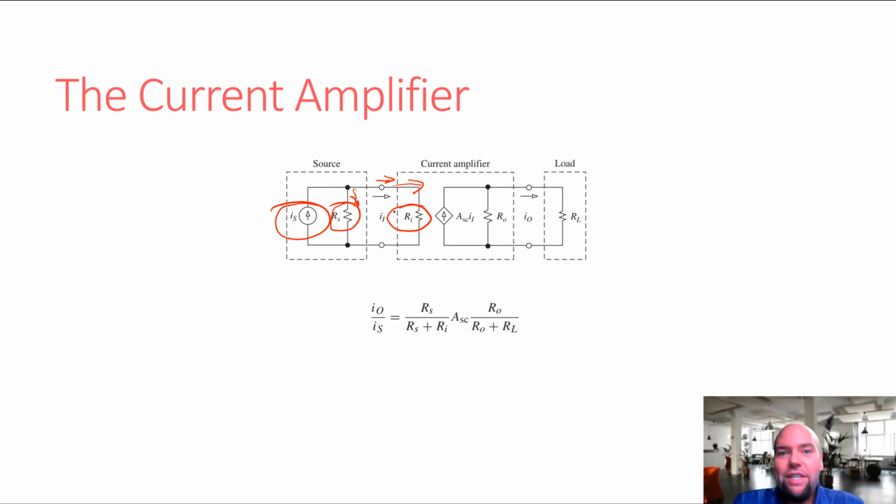But if you have a very high resistance, say you have 20 milliamps flowing into 10 kiloohms. Well, if you have 20 milliamps flowing into 10 kiloohms, it's going to take 200 volts in order to achieve that. Let me see if I'm doing that right. 20 milliamps, 10 kiloohms. Yeah, it's going to take 200 volts. So basically, that current supply is going to have to build up 200 volts to maintain that current. So currents are the opposite of voltages, or they're complementary to voltages.